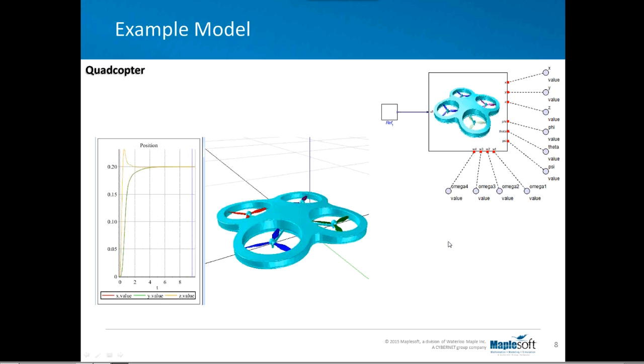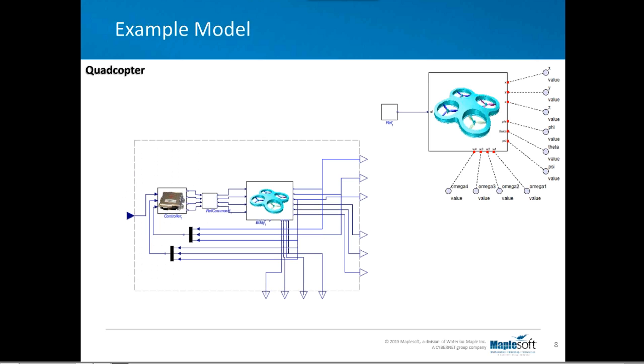which is where you can manipulate equations and do symbolic operations on the equations that define your MapleSim multi-domain model. And these steps can all be done symbolically and programmatically to get the definition for a controller. In this case, there's an LQR controller that is generated by getting the equations of the system, linearizing them, and then following the steps to find the gains that would stabilize the system.